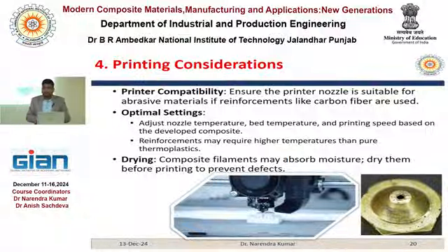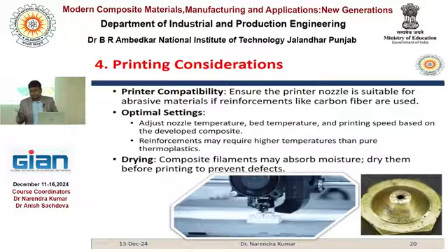So in that case, you can use good material nozzles, stainless steel nozzle, or other materials that are also available. So you can check the compatibility of the nozzle with that composite, and then you need to optimize the printing settings, like temperature, bed temperature, and speed. Otherwise, you will not be able to achieve the proper flow rate and proper adhesion.